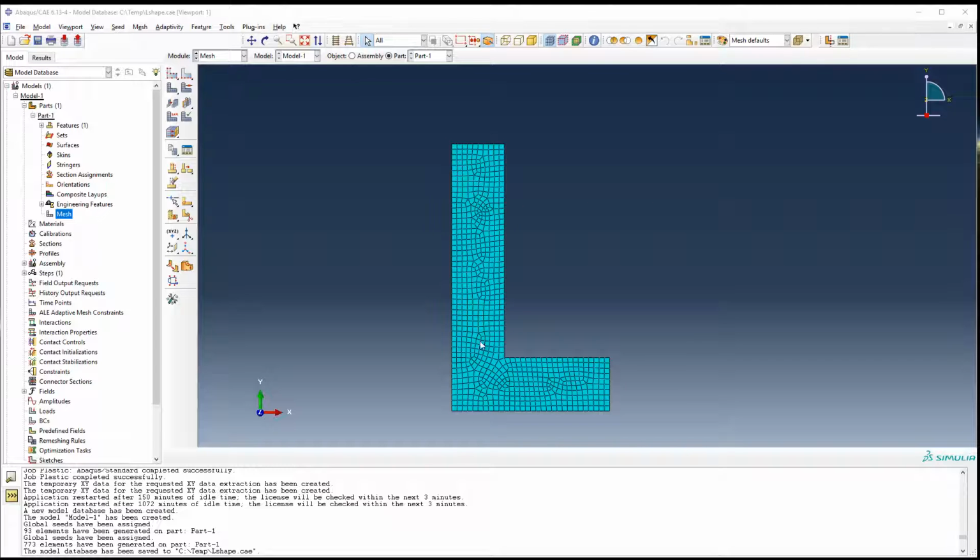The length of this is 50 millimeters. We're gonna pull this 30 millimeters, so it's a forced displacement, and we're going to see what resulting forces are going to be up here, and also where the material starts breaking apart. Okay, so let's start with defining the material.